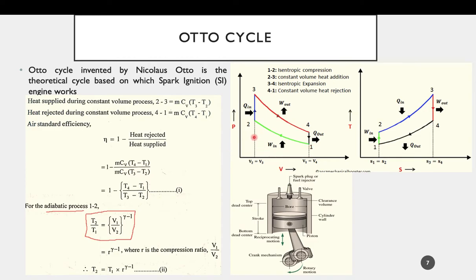The piston will move from state point 2 to state point 1. This is the maximum movement of the piston. So this might be the top dead center, 2 over here, and 1 over here will be the bottom dead center, and the piston will be moving between 2 and 1. That is evident from the PV diagram because the diagram is happening in between 2 and 1. There is no volume change beyond 2 and 1. So 1 to 2 is the region where the piston sweeps.